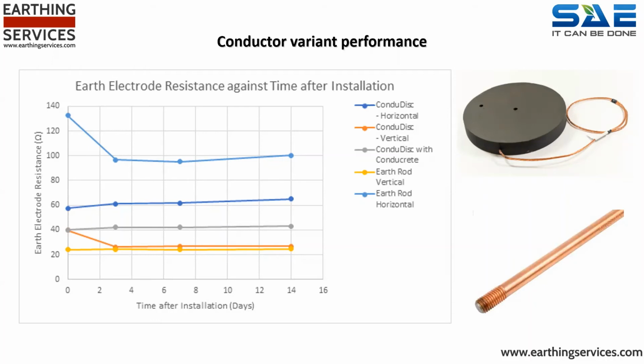What's the hidden factor? Think back to the differing soil model, which is the pertinent factor when considering that of the 5 electrode variants under test that were installed blindly, 4 of them were located almost entirely in that layer of high resistance, with only 1 penetrating the dramatically lower resistance of the layer beneath. Let's visualize that concept.